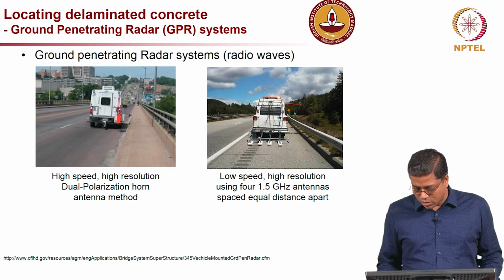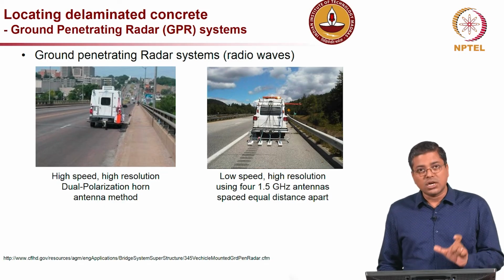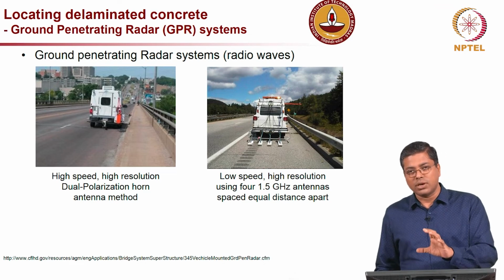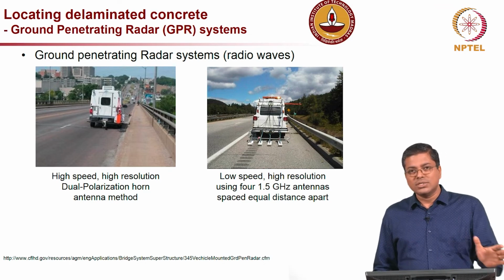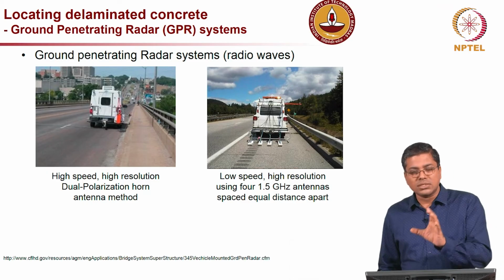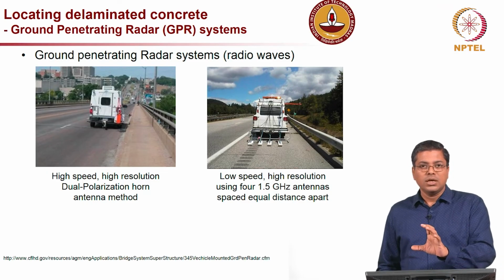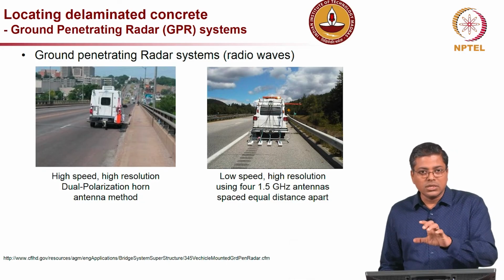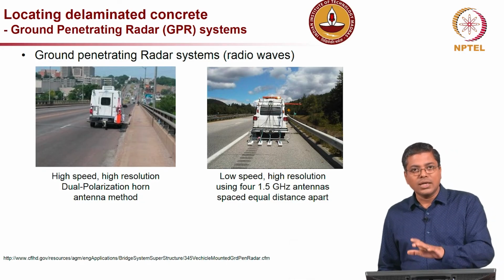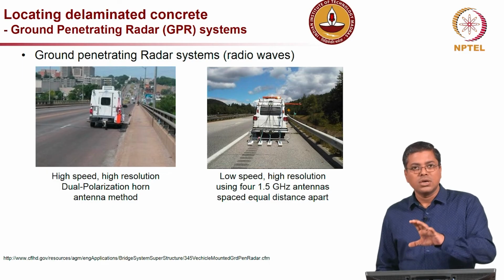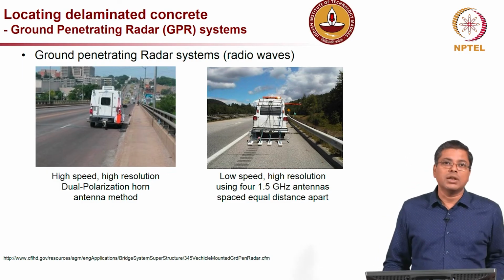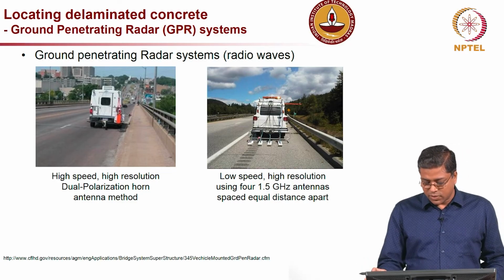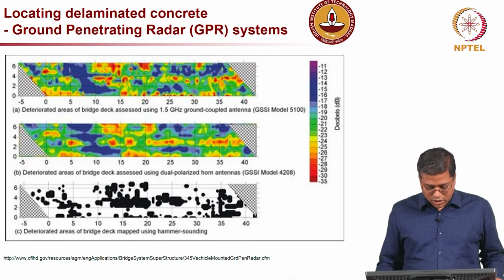So, you have to really look at the thickness and then make a judgment. When somebody says GPR based measurements or all these non-destructive type measurements, ask this question very specifically to the instrument manufacturer: whether this will give you good high resolution images on this particular type of structure, given the exposure conditions, etc. That is a very important question before just buying an equipment.